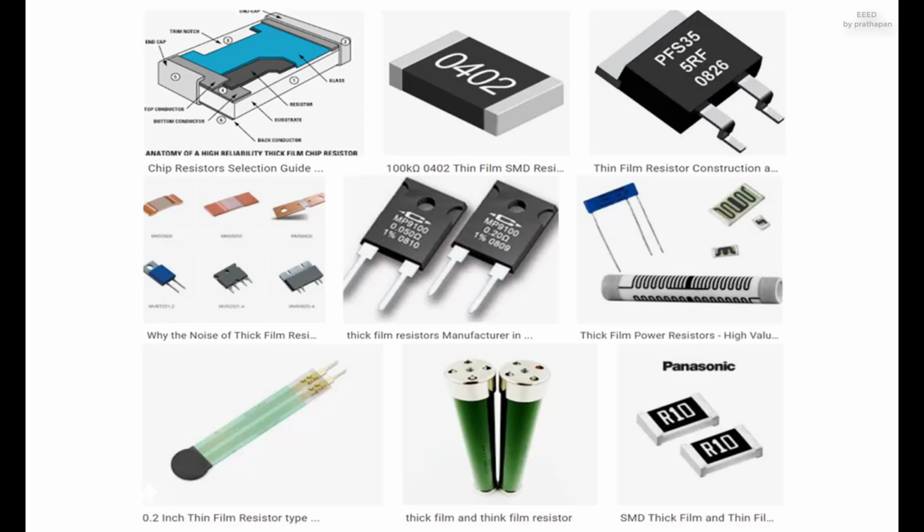Temperature coefficients of thick film resistors are high, typically plus or minus 200 or plus or minus 250 ppm/K. A 40 Kelvin, 70 degrees Fahrenheit, temperature change can change the resistance by 1%. Thin film resistors are usually far more expensive than thick film resistors. For example, SMD thin film resistors, with 0.5% tolerances, and with 25 ppm/K temperature coefficients, when bought in full-size reel quantities, are about twice the cost of 1%, 250 ppm/K thick film resistors.